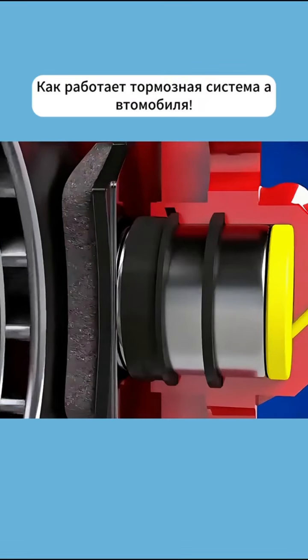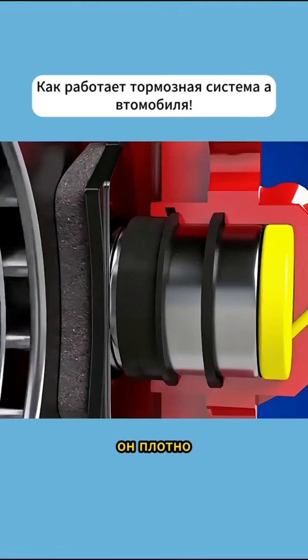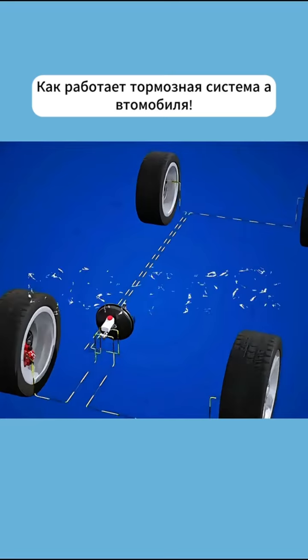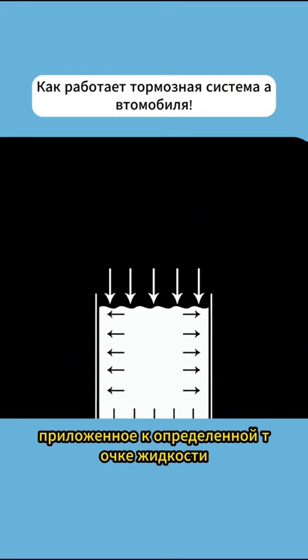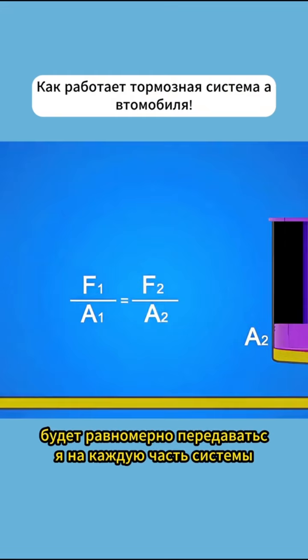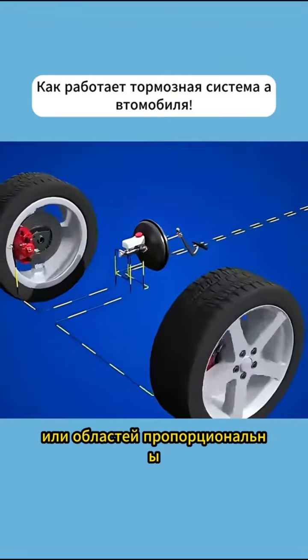Inside the brake caliper, there are one or more pistons. After the piston is subjected to the pressure of the brake fluid, it tightly presses the brake pads against the brake disc to achieve deceleration. The main principle of the hydraulic system is Pascal's law. That is, in a closed fluid system, pressure applied to a certain point of the fluid will be transmitted uniformly to every part of the system.